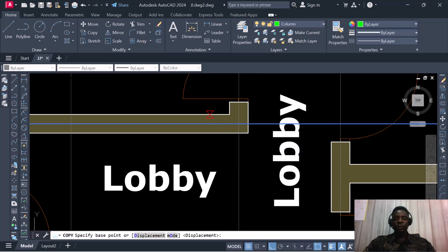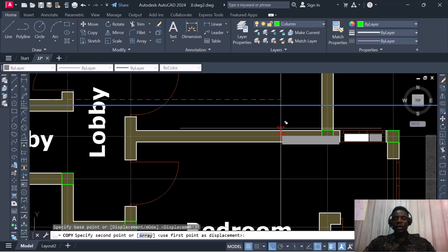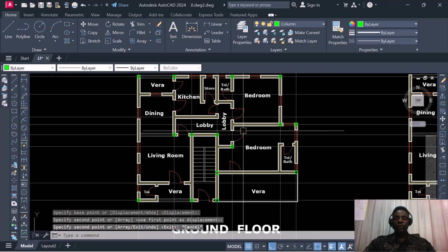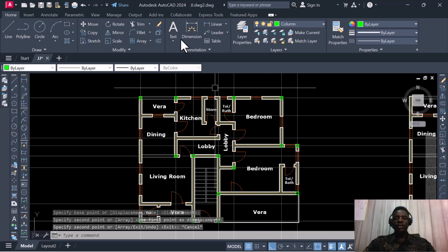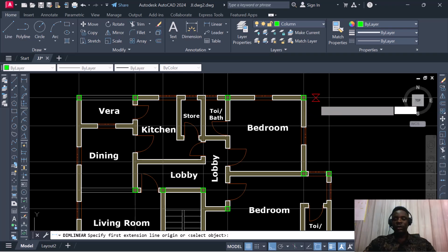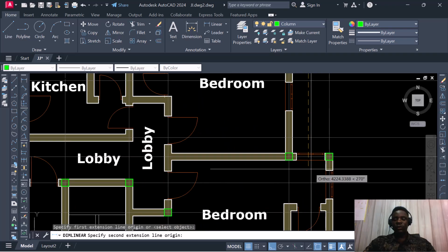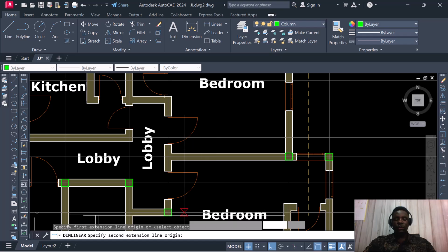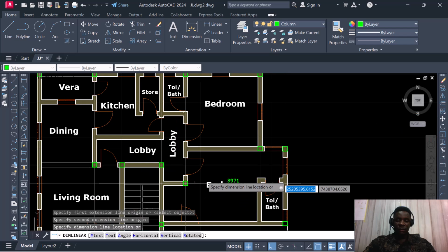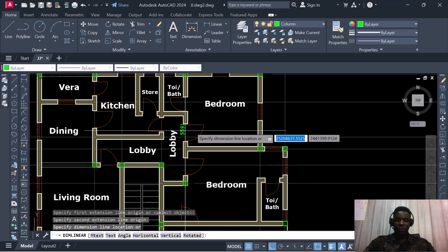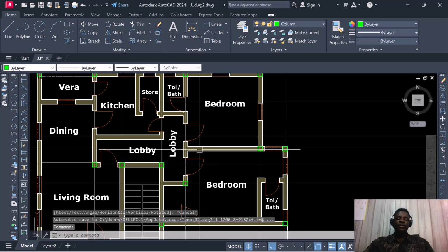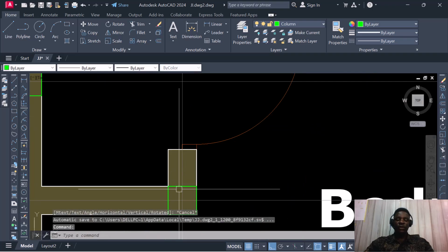for the beam. Okay, so here we'll be needing a beam over here, so we have to introduce a grid. Okay, that's why I have to copy and I'll paste here. So if we look at this length, what do we have over here? So we'll look from this other span down to what we have over here. Okay, so I want to check this distance. You can see I have 5.5 meter. So I need to introduce a column for the sake of the video.